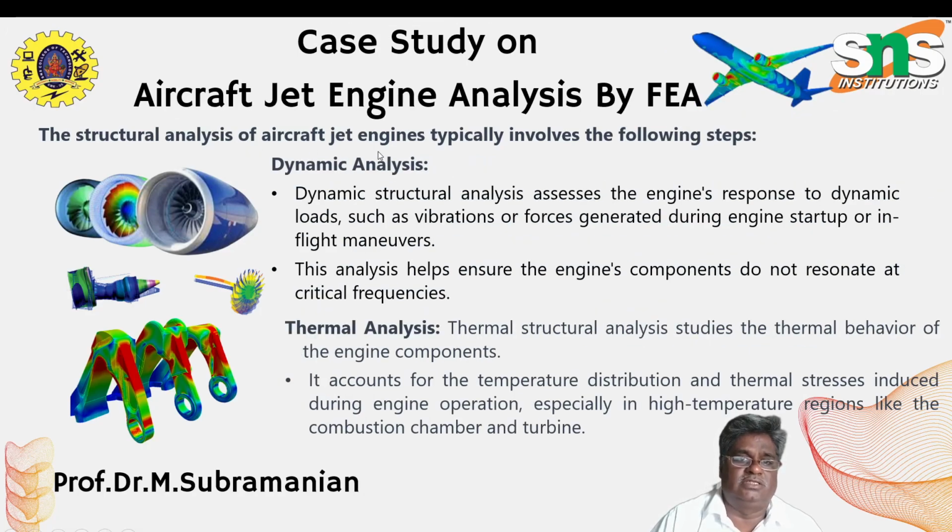A major point in the structural analysis of aircraft jet engines is dynamic analysis. Dynamic structural analysis assesses the engine's response to dynamic loads such as vibration or forces generated during engine startup or in-flight maneuvers. This analysis helps ensure the engine components do not resonate at critical frequencies.